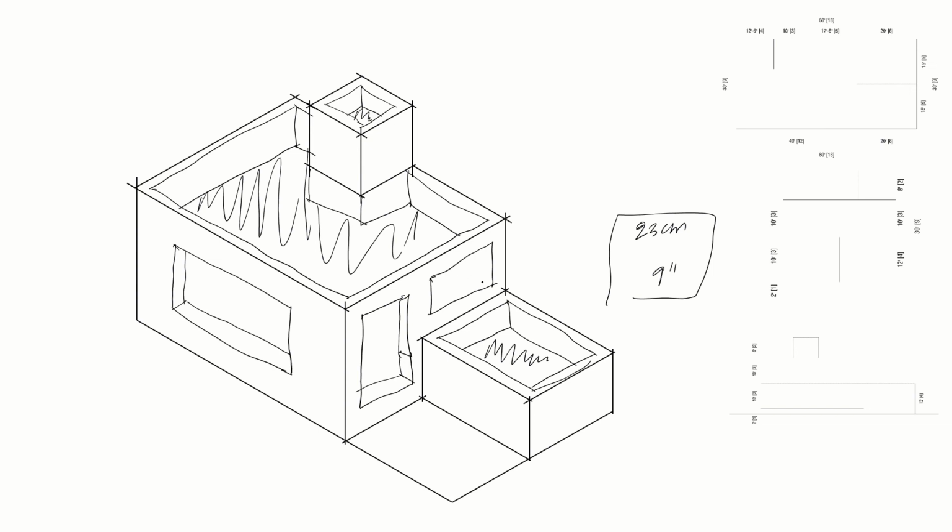If it is a window, it is not going to be 23 centimeters or 9 inches, it is going to be 3 inch or 4 inch, which is let's say 7 centimeters to 10 centimeters. So I'll show only a depth of 7 centimeters. This is only the opening.